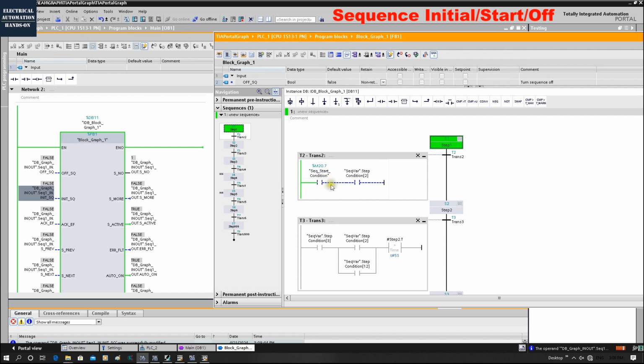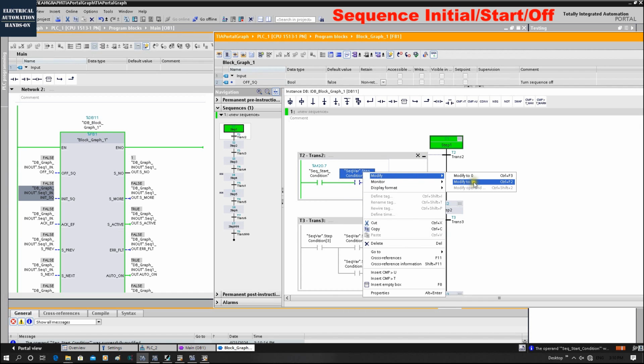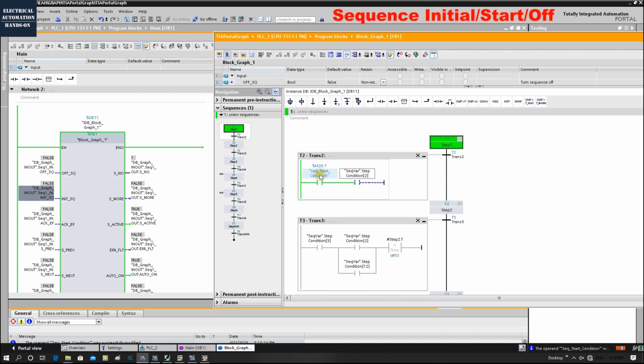So that's why usually I will use one sequence condition just below this step 1. Basically, it's playing the role of a switch, right? So once it's on, it enables this sequence to keep going. So this is the transition condition. If this condition is off, even when the other condition is on, it won't run, right? This works like a car engine, that ignition, that key.